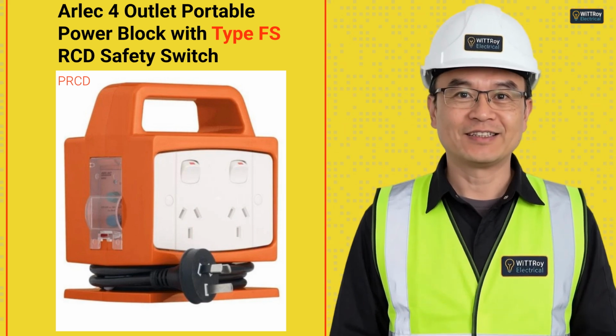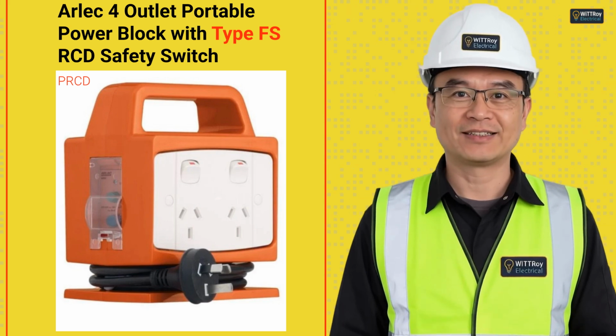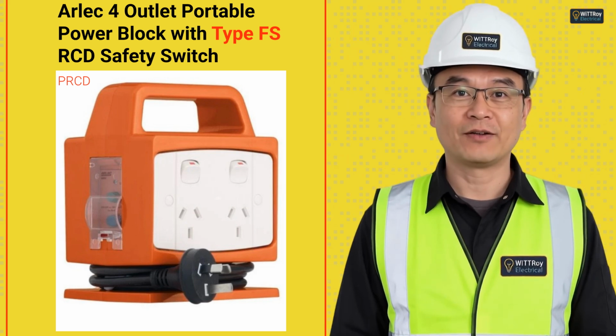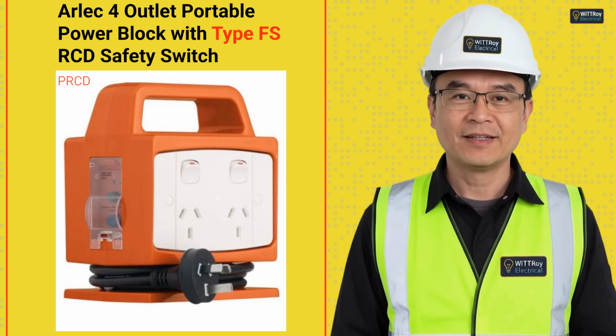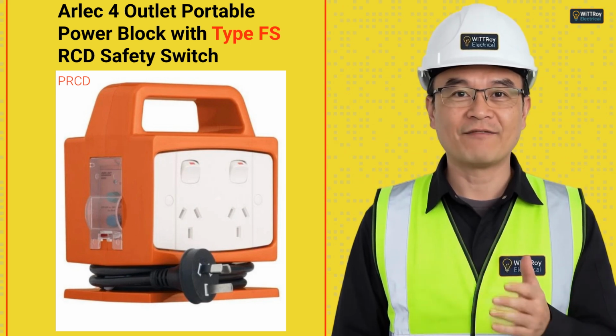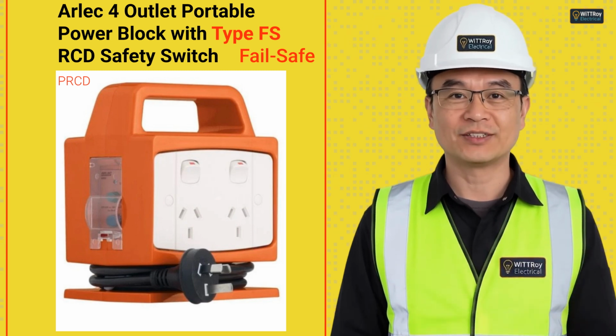Let's look at this device. This is an RLEC 4-outlet portable power block. It has a built-in Type FS RCD safety switch. Type FS is not the same as Type AC, Type A, Type F, or Type B. Those types tell us what kind of residual current waveform the RCD can detect. Type FS is mainly used on portable RCD safety switches. FS means fail-safe. It is designed to disconnect if the supply active or neutral is lost.